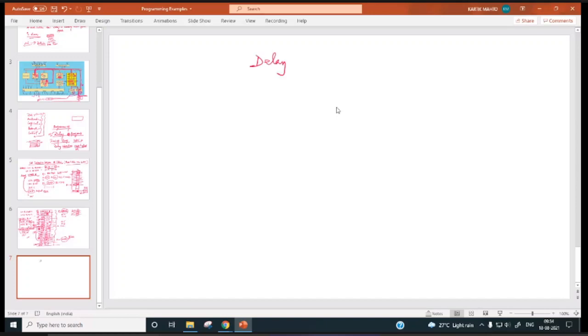The first instruction is MVI C, 46H. What exactly is this instruction going to do? Move immediate data 46H to the C register. So C will be 46.